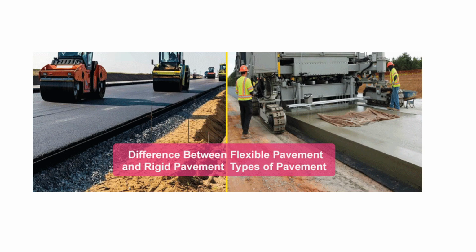For development of these types of roads, we need the actual levels of the top level of each layer and the carriageway width or roadway width. As we know, in the flexible pavement, the layers are subgrade, GSB, WMM, DBM, BC.